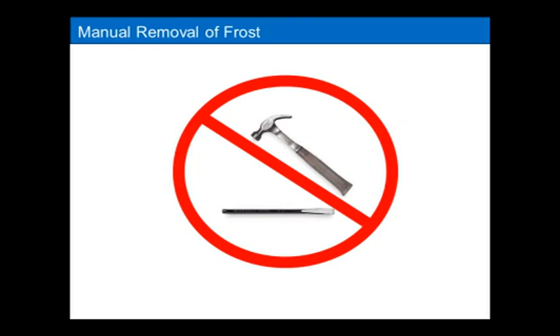It's an easy problem to realize. You'll just see this cake of ice and frost on the coil, and you're going to have to figure out why that's developing. But one of the things you're definitely going to have to do is get rid of that ice and frost manually. Before you leave that job site, you may have to go in and do some manual defrosting yourself.